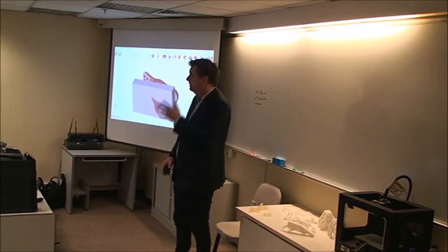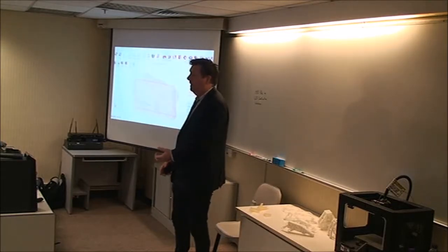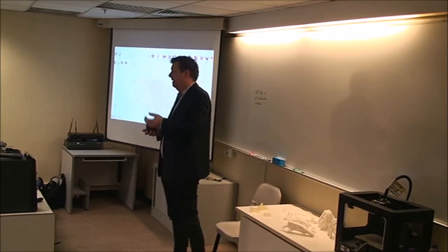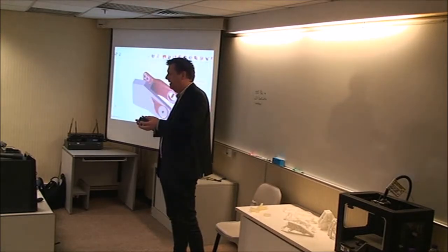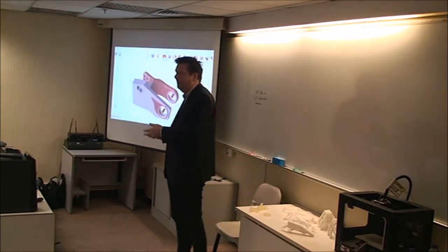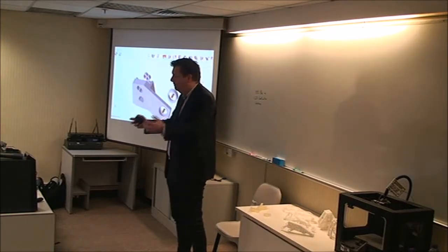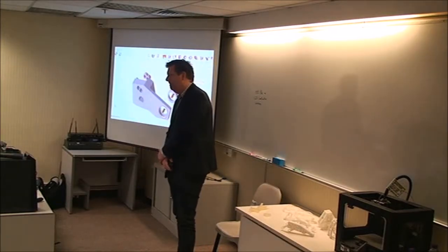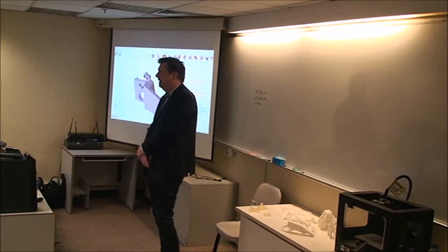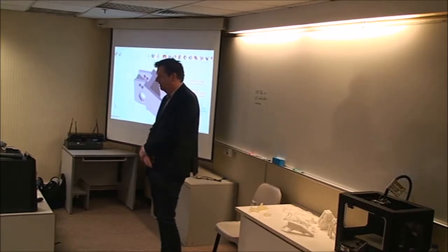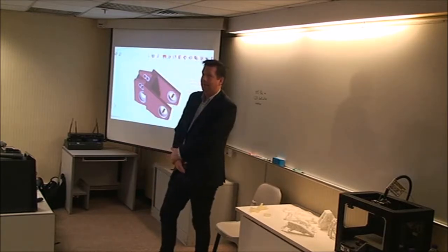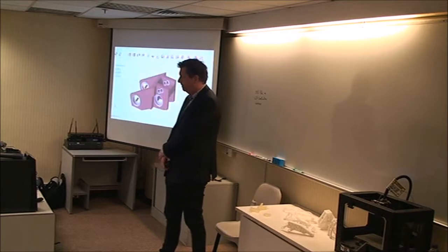That's good, but you've still got all those initial assumptions. It's better if you've got more package space. So again, if you've got a design at the beginning of your process with the maximum package space that still doesn't meet your design targets, it's good to know that early on. You can go back and, especially in automotive, you can argue, I need more space for my bracket, otherwise it's never going to meet your targets. So as much as possible, you build up and use as much design space as you possibly can. Within your package, that's potentially everything that's available to do your optimization on.